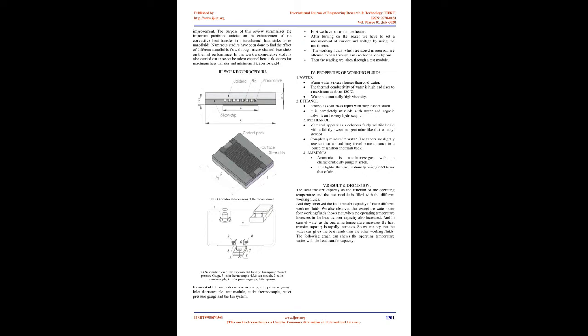The results showed that using phase change materials in microchannel heatsinks with different configurations leads to enhanced cooling performance of the micro heatsink. The phase change material should be selected according to its melting temperature for the certain application, as different phase change materials cause different values of reduction in heatsink temperature in the range of ambient temperature due to differences in melting temperatures of PCMs. The cost of materials depends on the classification of the PCM, organic or inorganic, and the quantity of PCMs used in a certain application too.